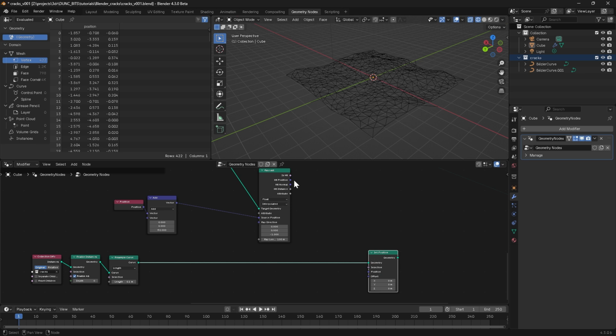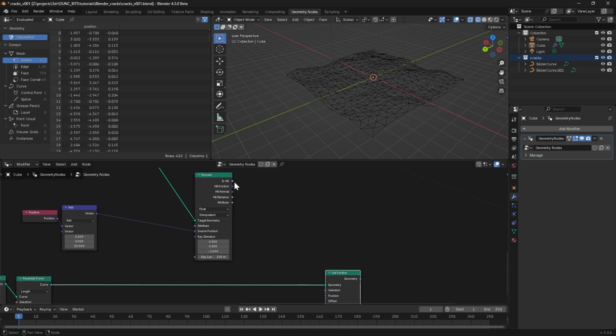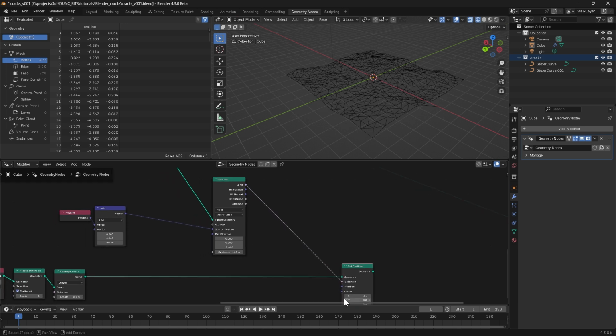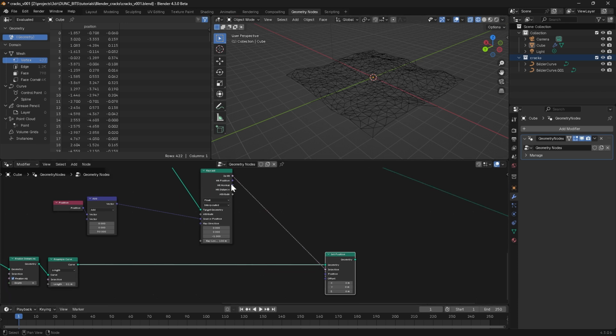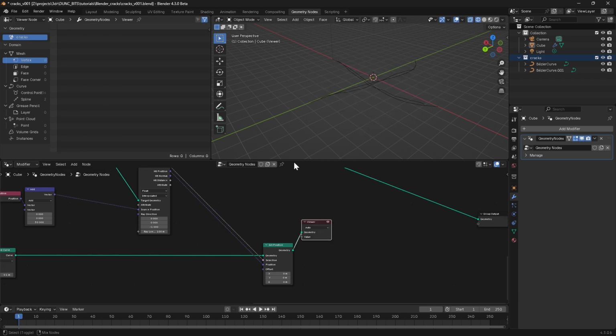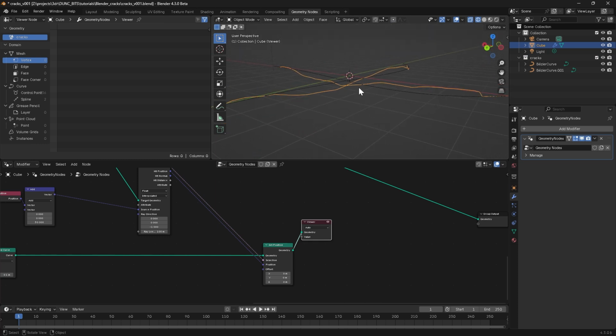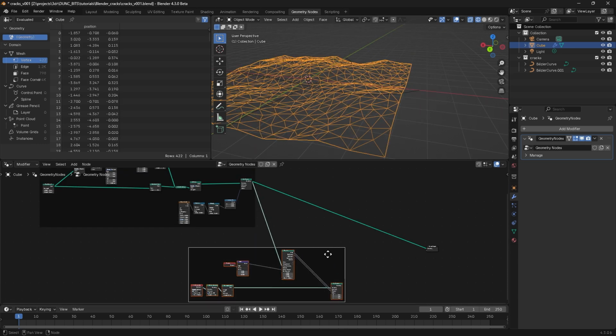We only want to set positions on points which register a hit. So I plop that into the selection, and the new position is going to be whatever the hit position is. So we drop that into here, and let's have a quick look at our curves just to make sure. Yeah, they are now following the ups and downs of our terrain, and any points that overshoot are not being affected. Let's add these to a frame. Again, give it a label. So we'll do curves to terrain.